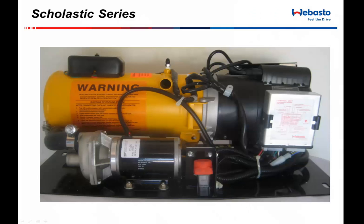We'll send a signal to a 12-volt motor, which is located underneath this black shroud. That motor will start turning, and basically it's driving an internal fuel pump and an internal combustion fan, and getting the product ready to operate. We'll be taking this thing apart to let you look at the inside. That fan motor is driving both air and fuel, prepping the unit to start operating. After about 20 seconds, you'll hear the unit light off.